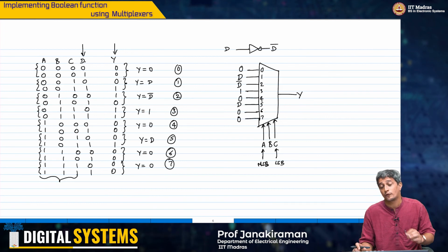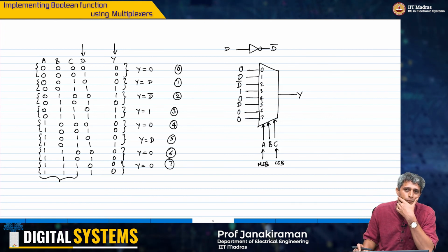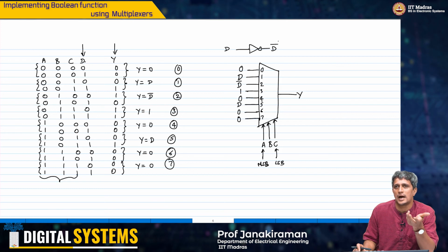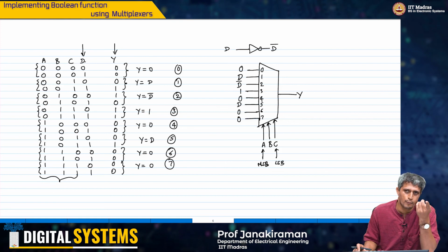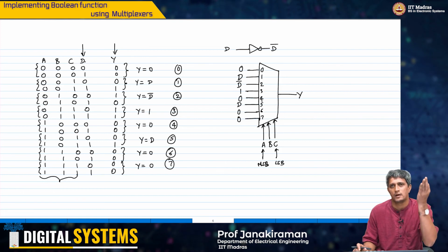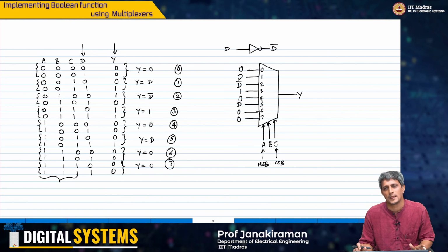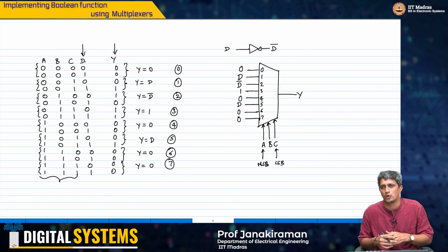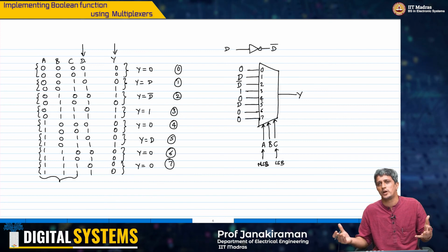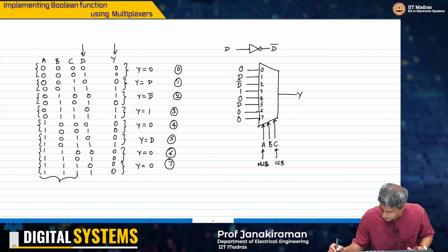Of course, if you need to implement a 5 variable logic function and so on, then you have to build at least a 16:1 multiplexer, and then assign the inputs to either 0, 1, or the fifth input or its complement. That's the essential idea behind implementing arbitrary Boolean functions with decoders and multiplexers.